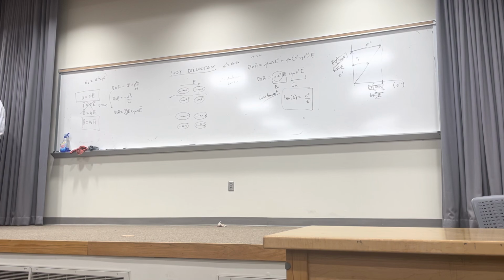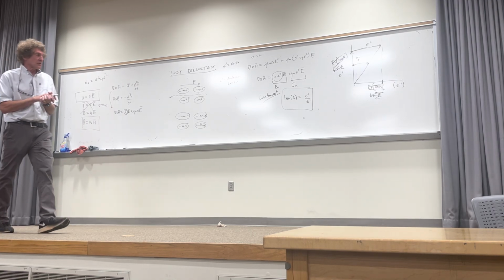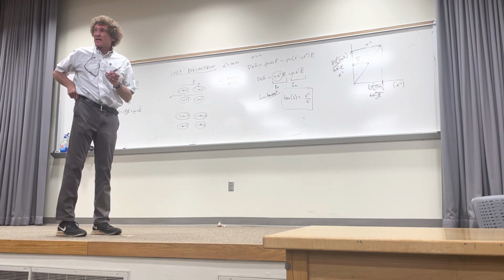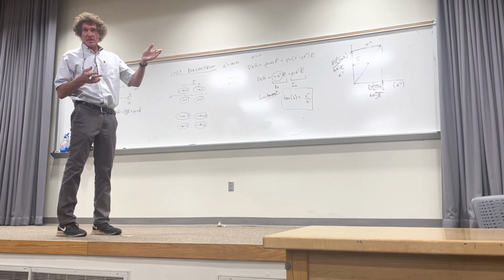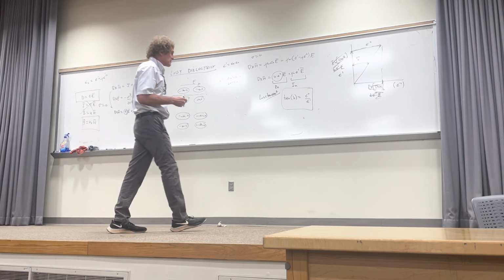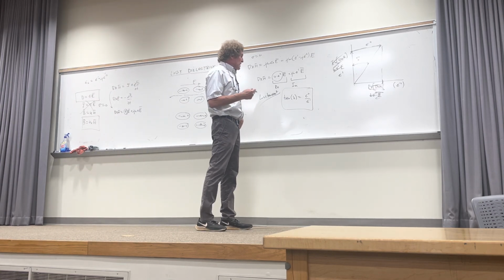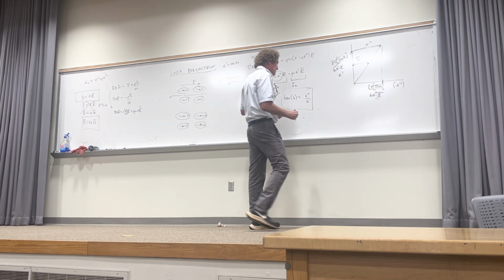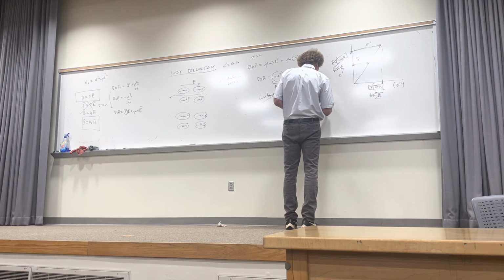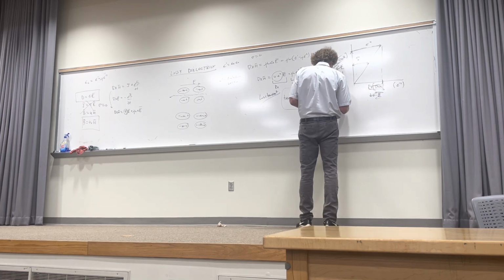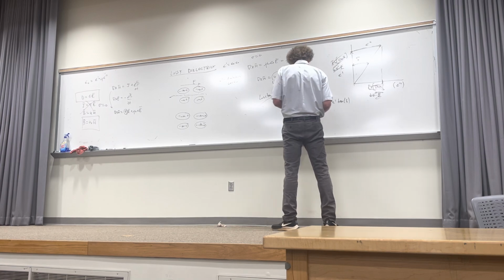But in the real world, when you're dealing with lossy materials, you would like to see an example of a real problem. And I can give you one later where you're designing a capacitor and you've got to select materials to create this capacitor. It's going to be a conformal capacitor. It's part of an overall circuit. But this is the real thing that you have to deal with. So obviously, epsilon double prime is simply equal to epsilon prime times the tangent of that angle.